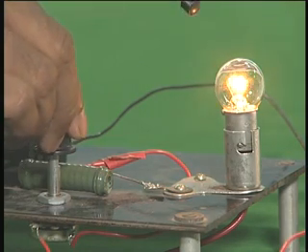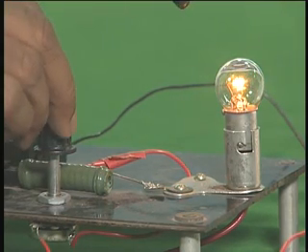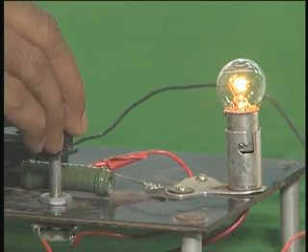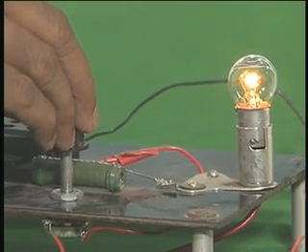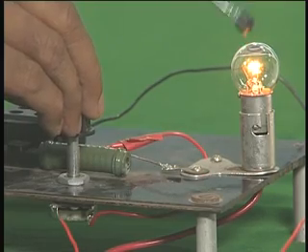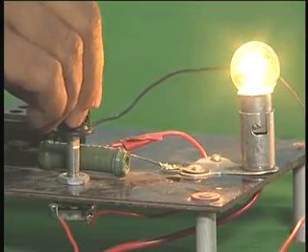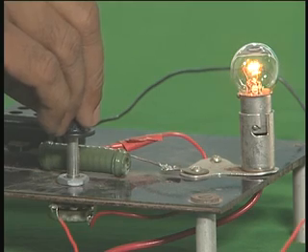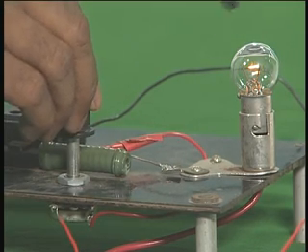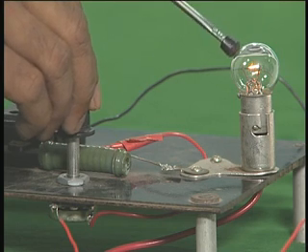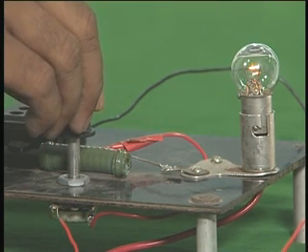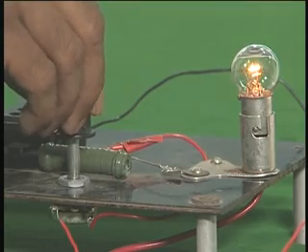That means the energy dissipated in this potentiometer is very small, because it is in the gate circuit, which is only handling a few milliamperes of current. But the voltage applied across the load is a large voltage, and that can be controlled very easily using this arrangement. This is the knob that you see in a fan regulator also, but the circuit there will be slightly more complicated, because it is an inductive load. You have to use some filters, because what you get ultimately will be a pulse of different things.